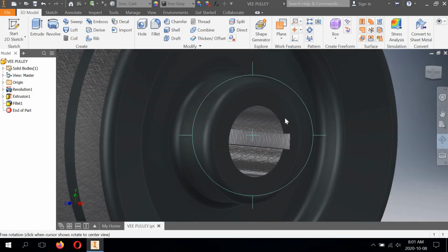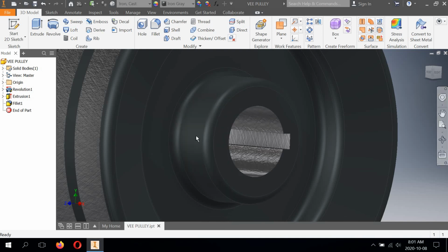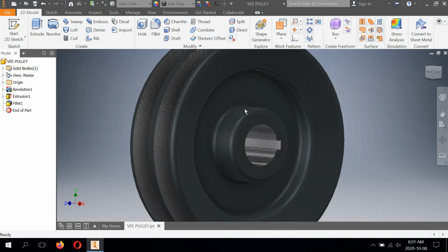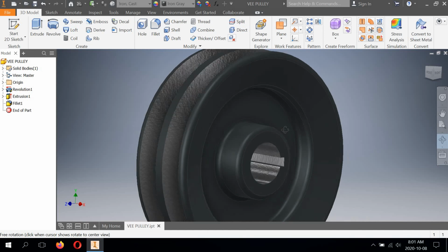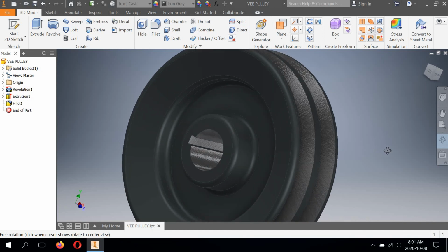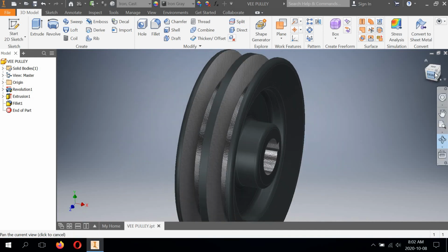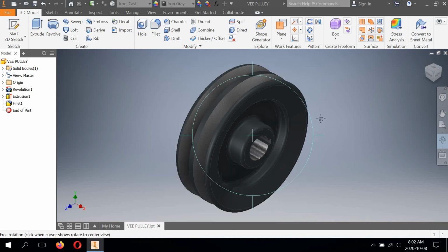So again, we don't put a fillet here where this hub face meets the bore, because we're basically drilling into this thing and then boring it out smooth and adding a keyway. So I hope that explanation makes sense. Some students have trouble understanding that. Most don't. So I think you should kind of get the swing of what we're doing here. But that completes that model fully. So that's what I want you to do with this today.